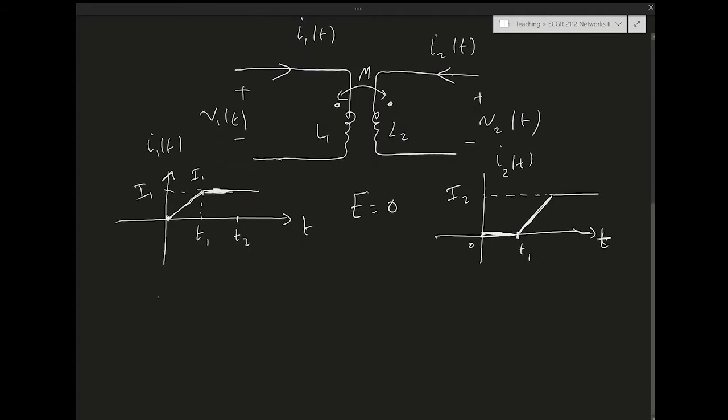So let's start with the time period 0 to T1. What's happening in that time period? Well, I2 is 0, so there is definitely no energy being extracted. Let's think about it this way. Any amount of energy that ends up being stored in this configuration has to come from outside of it. Energy cannot be created out of nothing. Energy can only be moved around. So it has to come from any circuitry outside. We could have sources outside, testing apparatus that pours energy into the setup.